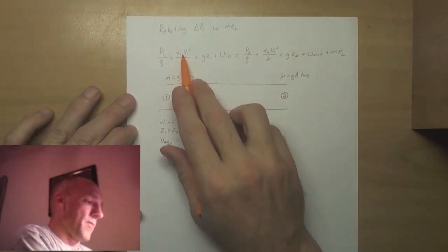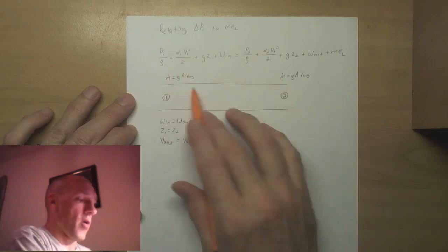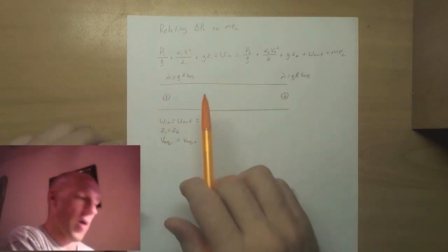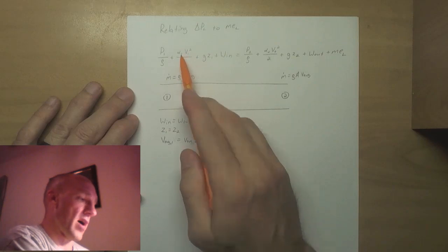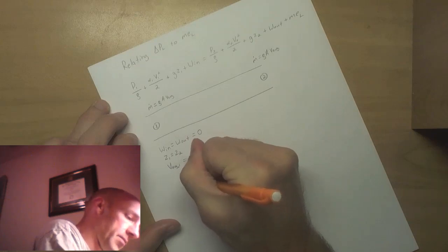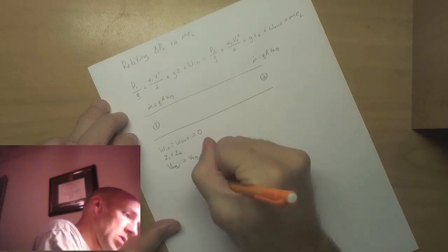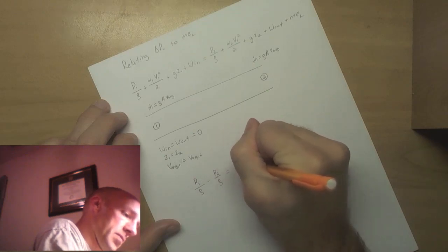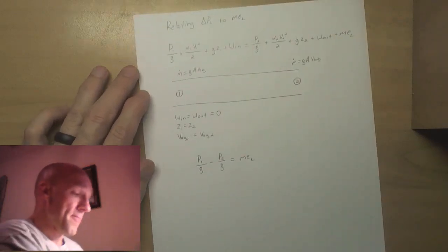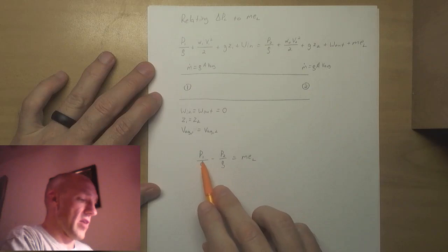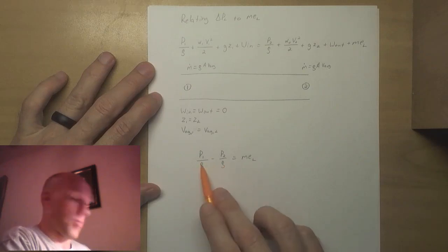So the velocity profile is also essentially constant. If all these parameters are remaining constant, the velocity profile is remaining constant, so these alpha values are going to remain constant. So this whole thing simplifies down to: the mechanical energy lost per unit mass is equal to the difference in pressures divided by the density.